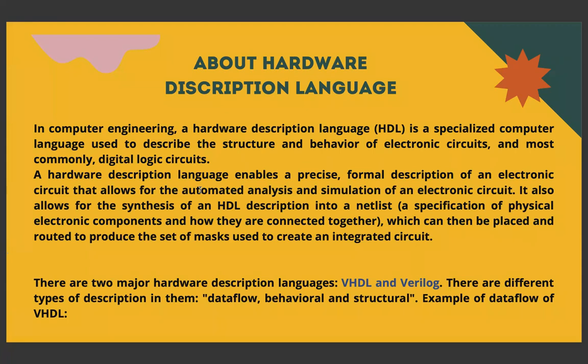Data flow level is what you write with an intent; you know how the data is flowing. Behavior level is where you write something like a C program, writing functions to it. Structural is like writing things in assembly language, where you should know what physical elements or gates you're using, and then use those blocks and create the logic. As designs go more and more complex, we mostly use data flow and behavioral models, though there are some places where we might be using the structural model as well.